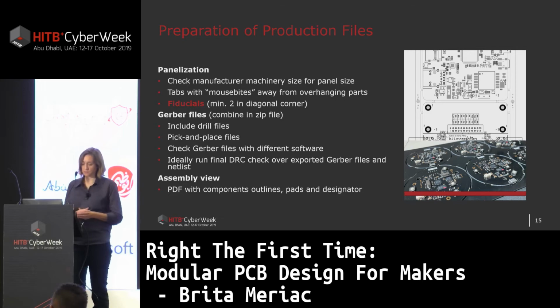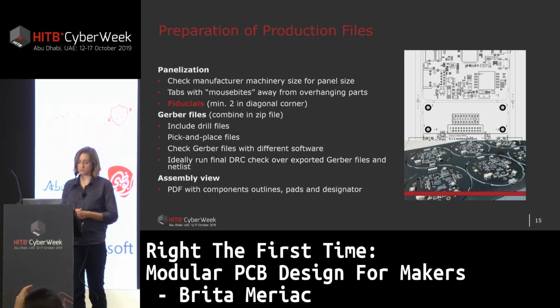The PCB manufacturer needs the board data as Gerber files, which includes the drill files, and the assembly house needs your pick-and-place files. Both can be exported from your layout software, and I recommend to check the exported Gerber files again with a dedicated Gerber view software, so that you see exactly the same data as the manufacturer sees.